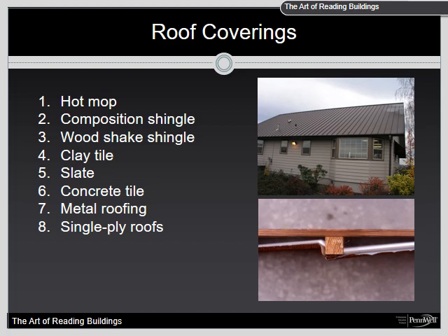Wooden shake shingles are just that. They are wooden shingles that are nailed to the roof. Problems with this type of roofing is, even though they're aesthetically pleasing, they traditionally don't last as long, usually less than 15 years. And they can be a high fire load. Sometimes they're treated, sometimes they're not. But a lot of times with these, once they start catching fire, you run into exposure problems because they basically start floating off in the wind and landing embers on other structures and yards, creating a whole bunch of spot fires.